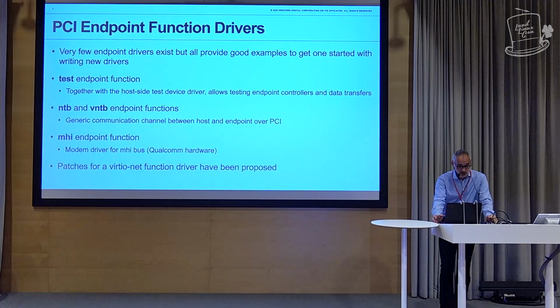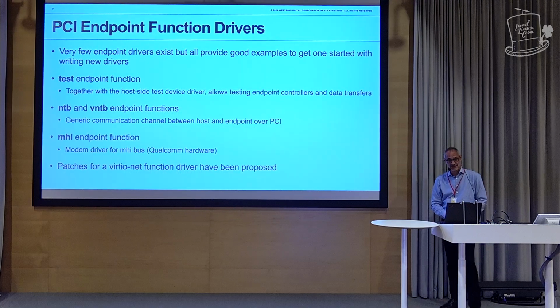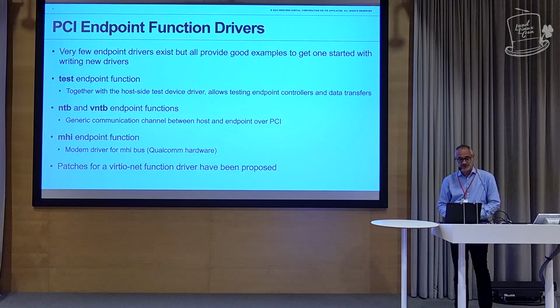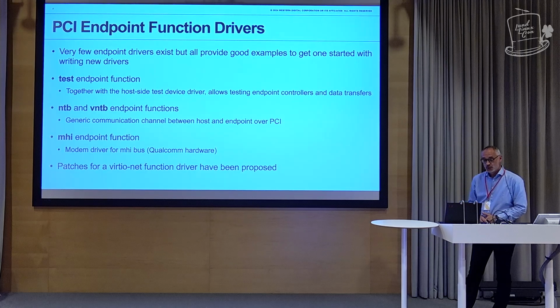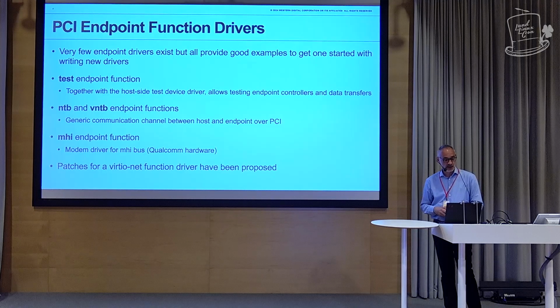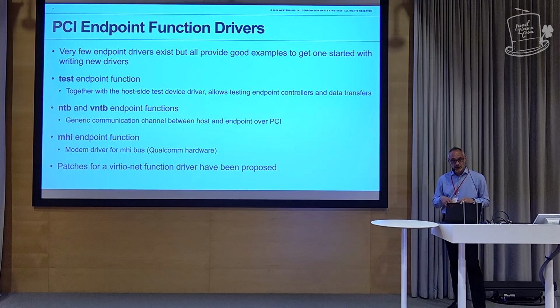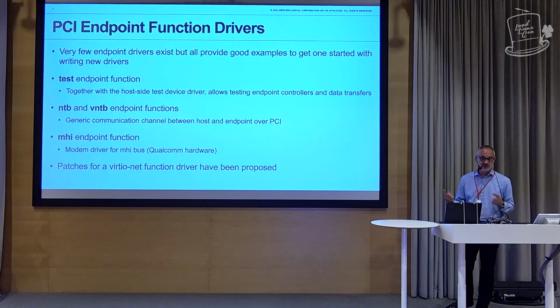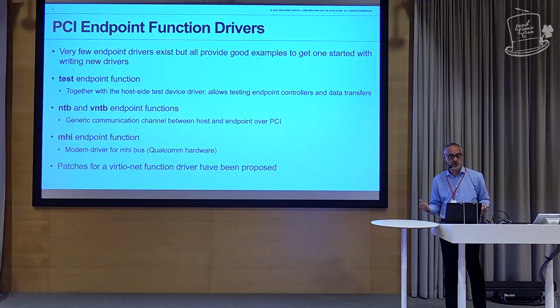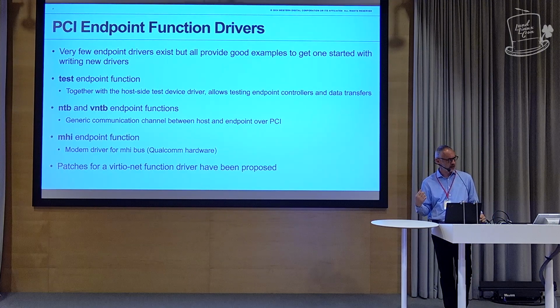For the function drivers, there's not a lot. There's one very useful, which is the test endpoint function. It is an endpoint function driver that creates just a dummy device, which can be served on the host side by the counterpart driver that is also with the kernel, and that allows you to test data transfer between the host and the endpoint, as well as interrupts and bar accesses.